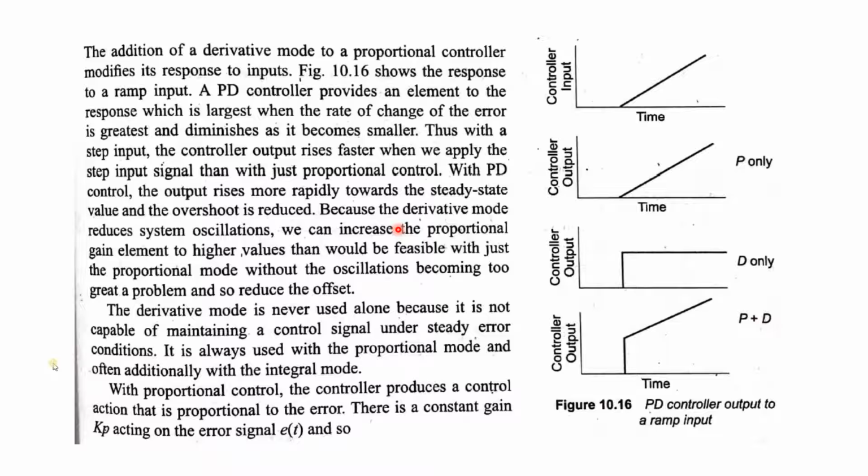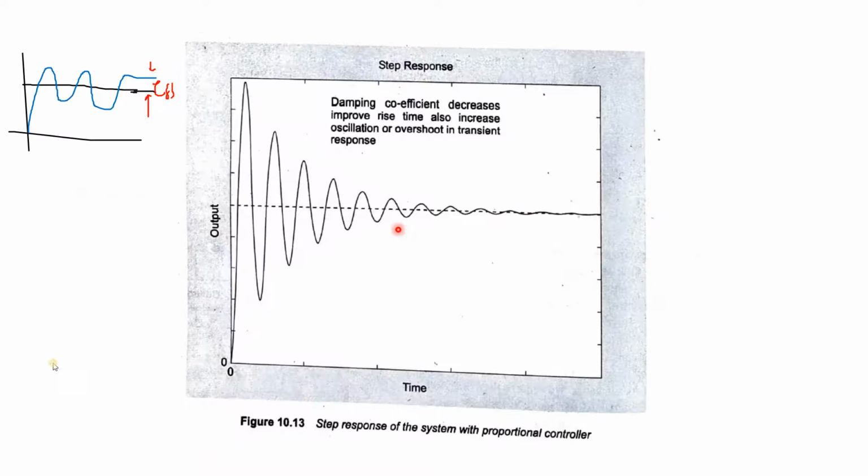That means in the water level controller, we have seen that if the tap from the bottom is open and water is running out at a faster rate, what will happen? The proportional controller will produce the proportional gain, but if the rate of decrease of the water is increasing, then the proportional controller cannot help over there. So it has to supply more and more magnitude of signal. So the overshooting will be huge.